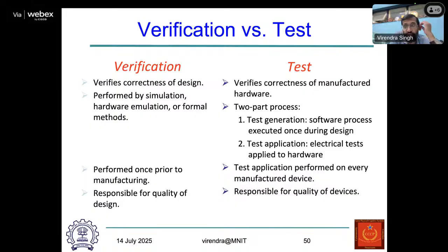This process will verify whether your design has any bug or not. However, test verifies the correctness of manufactured hardware, that whatever gate level netlist I have designed, whether that gate level netlist has been implemented or fabricated on the chip or not.